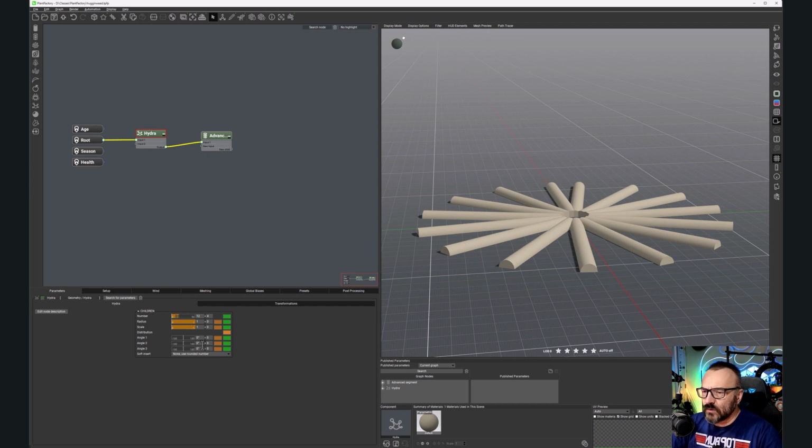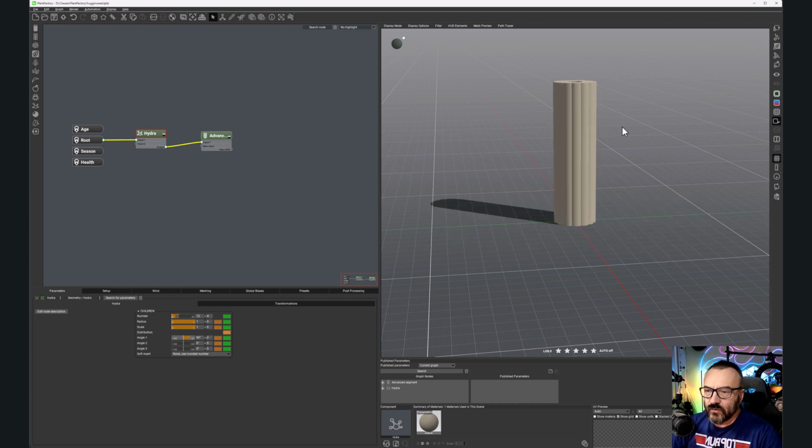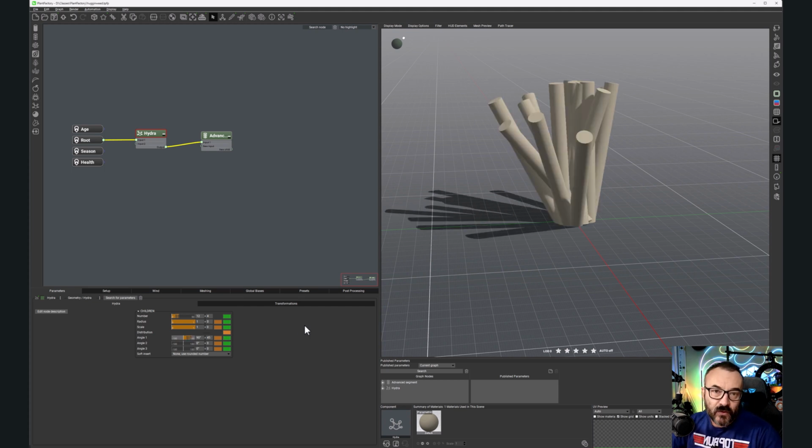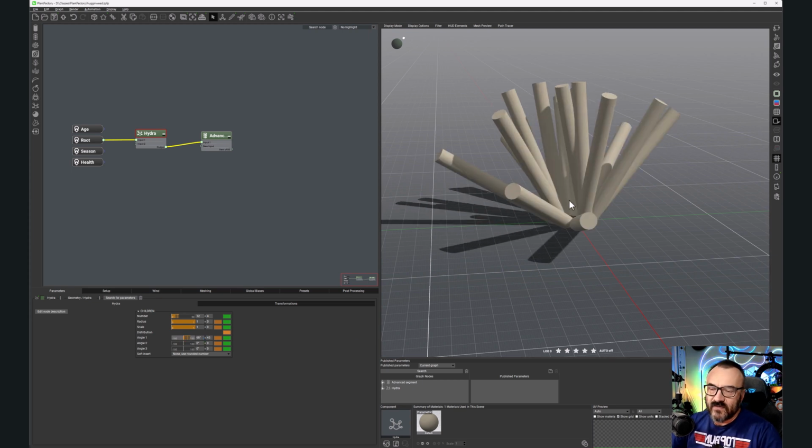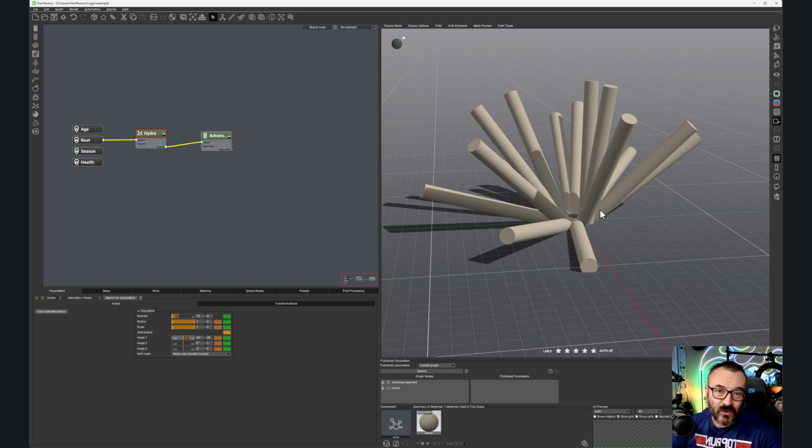Okay, let's go next. We'll change the angle a little bit because I want them going up for this. For angle 1, we'll just put 90 degrees, and you can see it goes straight up. But I don't want them all to be like this. So we'll add a 45, so it can be anywhere from 45 to this. If you think this is still a bit too straight and you want it a little bit flatter, we can always put maybe 60. Let's put 60. Then they spread a little bit more, and you can play around with this more and more. If you want them on the top and more spread around, you can always reduce this to about 45, and then you have it from 0 to 45, almost open, with the circle open in the middle.